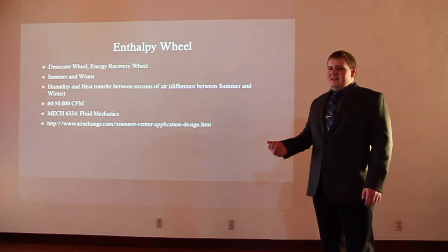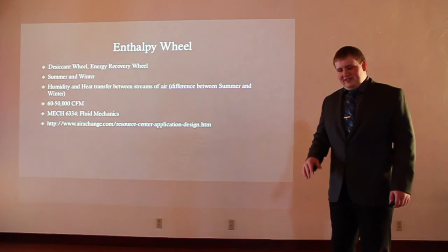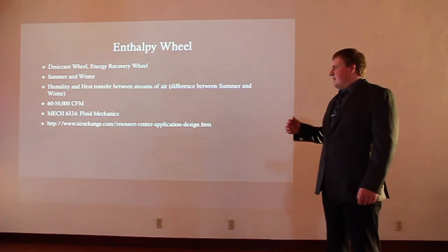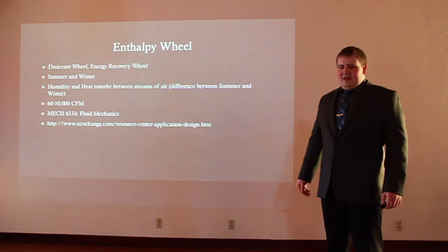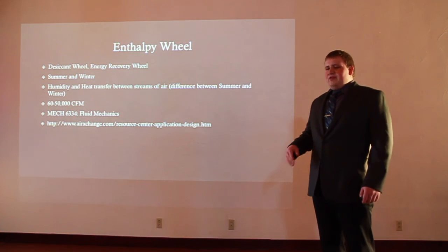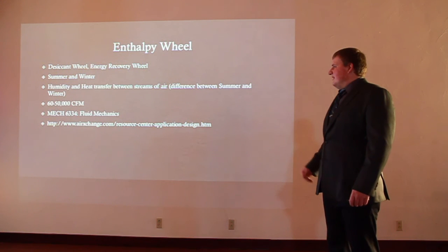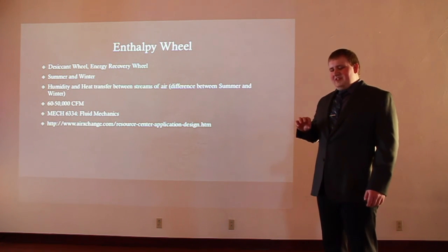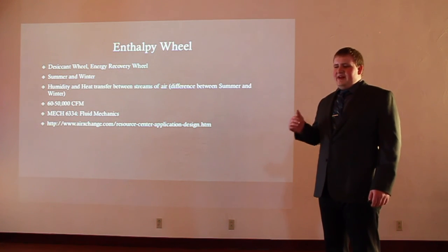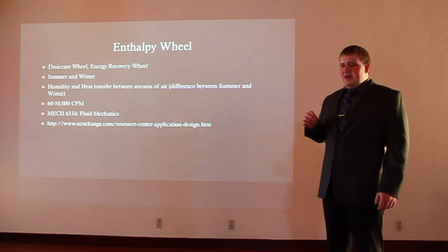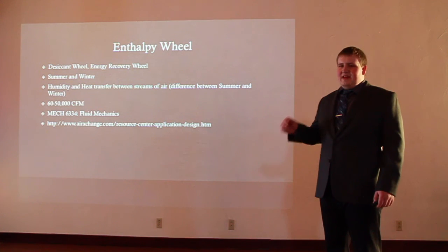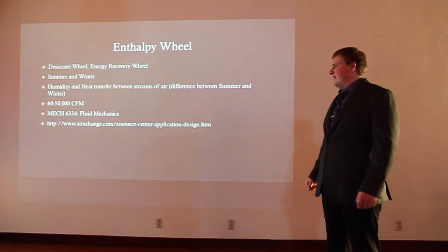They are put in place in the ventilation air handler for the system, where you can pre-treat the incoming air before it gets air conditioned for the building. This allows heat and humidity to be transferred between the incoming and the outgoing air, all dependent on whether you want the inside air to be hotter than the outside air or colder than the outside air.